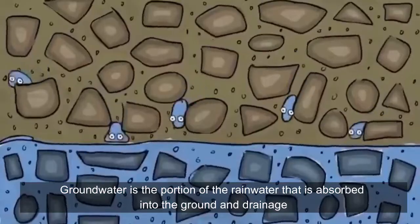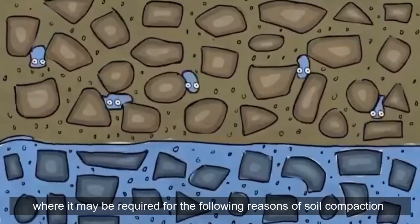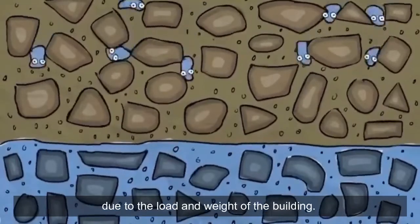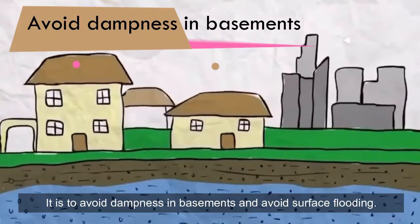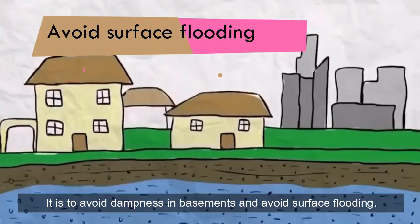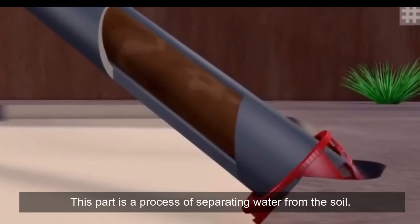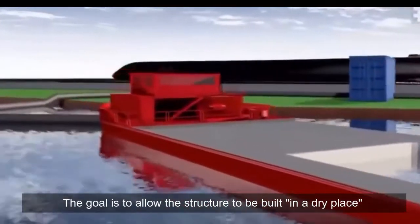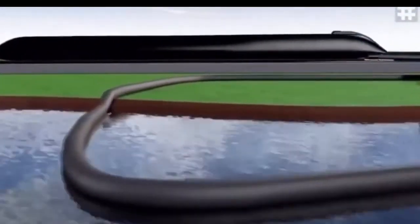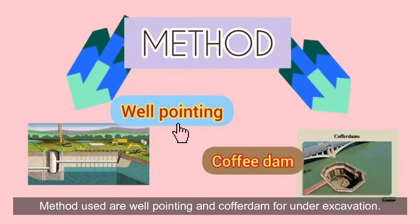Groundwater is the portion of the rainwater that is absorbed into the ground, and drainage may be required for the following reasons: soil compaction due to the load and weight of the building. It is to avoid dampness in the basements and avoid surface flooding. Site dewatering is a process of separating water from the soil. The goal is to allow the structure to be built in a dry place. Methods used are well pointing and cofferdam for deep excavation.